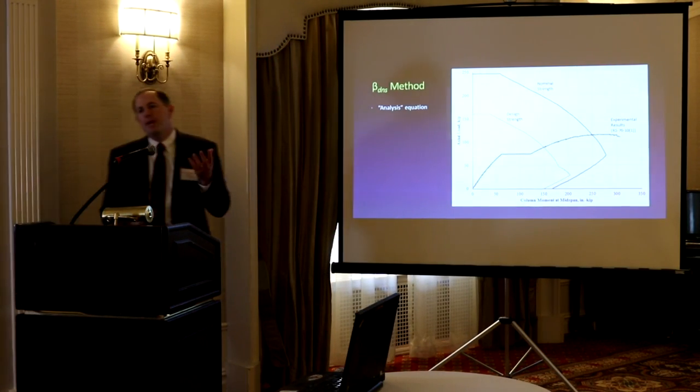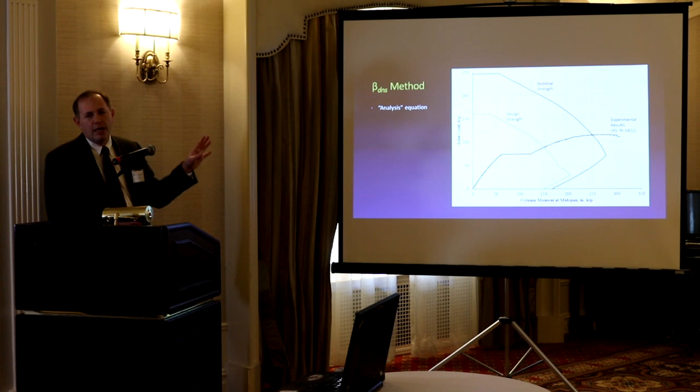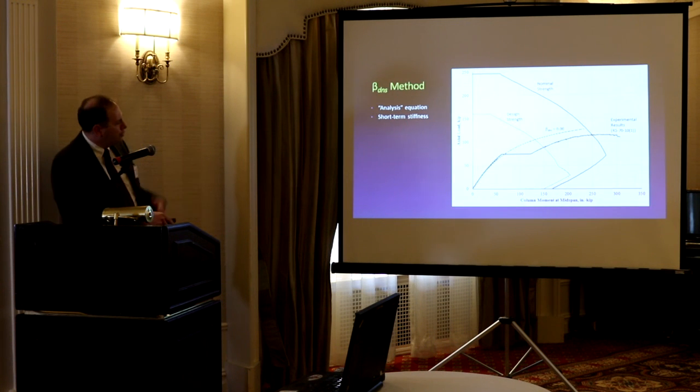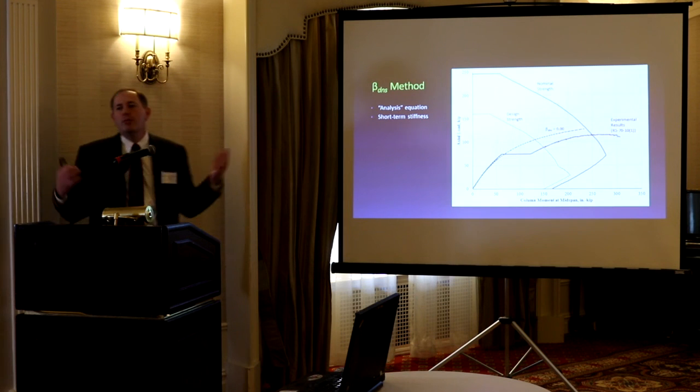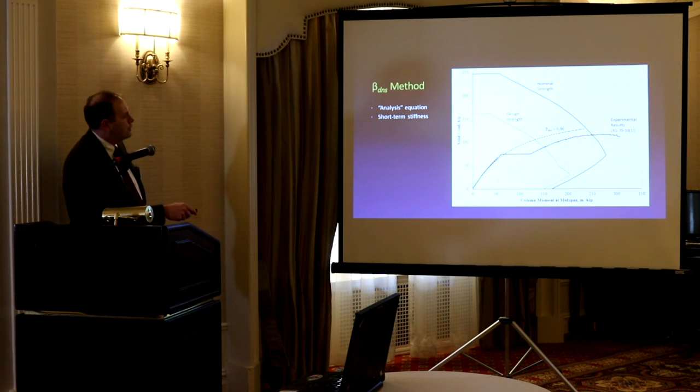So let's talk about the beta DNS method that's in the code. This equation is what we use because that was a little better than design. We were trying to figure out how to get there closer. So that's coming up here, and I mentioned it does pretty good. This is beta DNS is 0, meaning there is no sustained load effect. Short-term stiffness, there we go, and we fit.